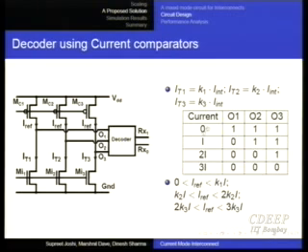Okay? So what I am suggesting is that you have 3 mirrors from the previous circuit and you have a reference IRF1, IRF2, IRF3, and since it is a current mirror opposing a current mirror, whichever current is high, it will just swing, it will charge some voltage to either VDD or to ground. So now you will get a voltage mode signal, and now you can put a decoder which will say whether it is.